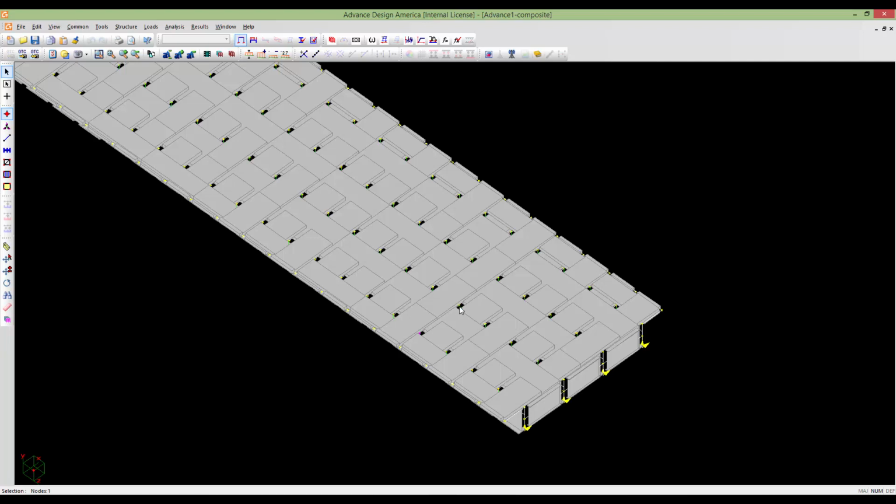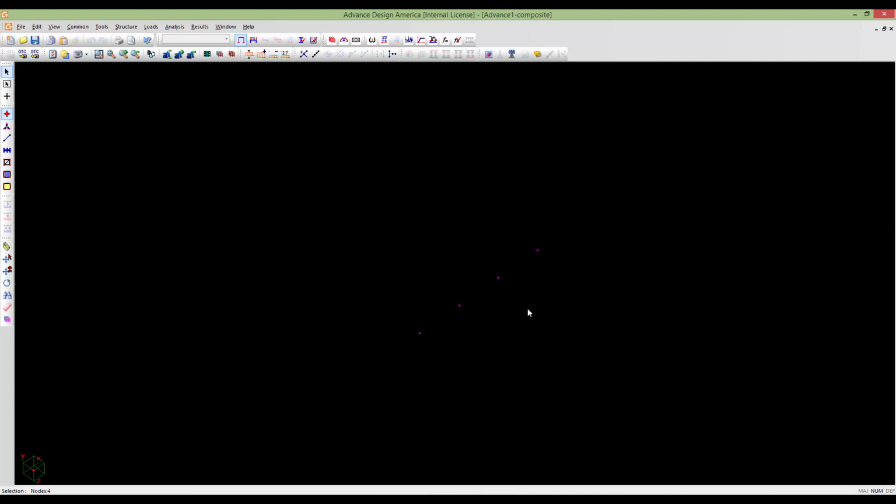on the main beam. Mask. And we will build the diaphragm using these 4 nodes. So firstly, we need to build these vertical rigid links, which models the web of plate girders.